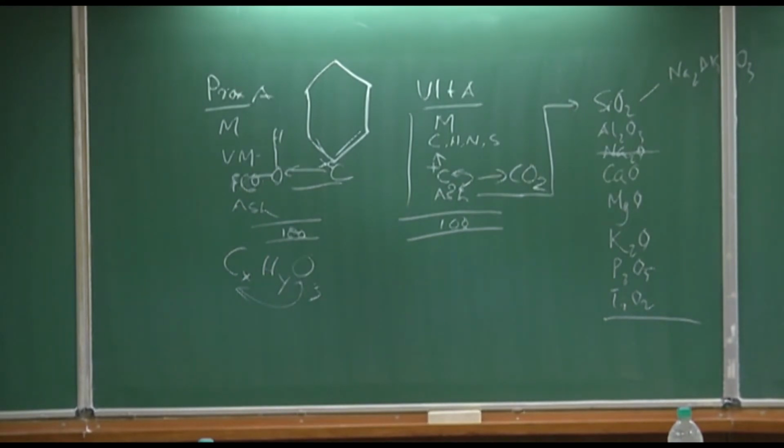Technically, if you take a piece of coal and continue to heat it to a high temperature for a sufficiently long period of time, all you will be left with is some amount of fixed carbon, almost pure carbon, plus the ash, nothing else. Nitrogen will be gone, hydrogen will be gone, oxygen will be gone, mostly sulfur will be gone, and only ash and the carbon will remain.